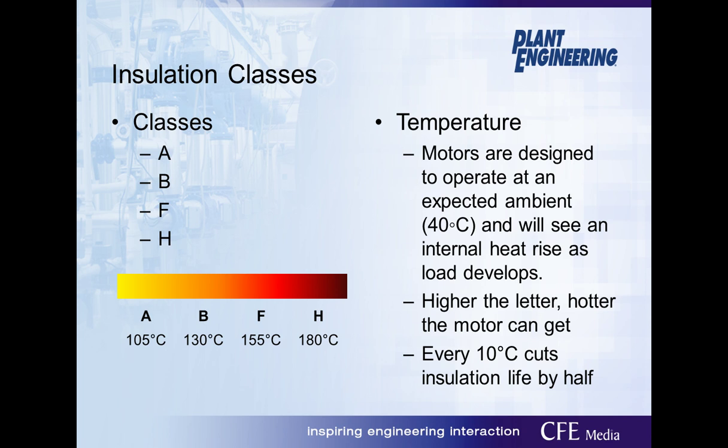Motors will be rated with an insulation class, which applies to the insulation on the windings or electrical wires, but bearings and other components will also be rated at temperatures above this insulation class rating. Looking at NEMA rating specifically, the higher the letter, the hotter the motor can get. In other words, Class H insulation is rated to run at a higher temperature than Class F insulation.